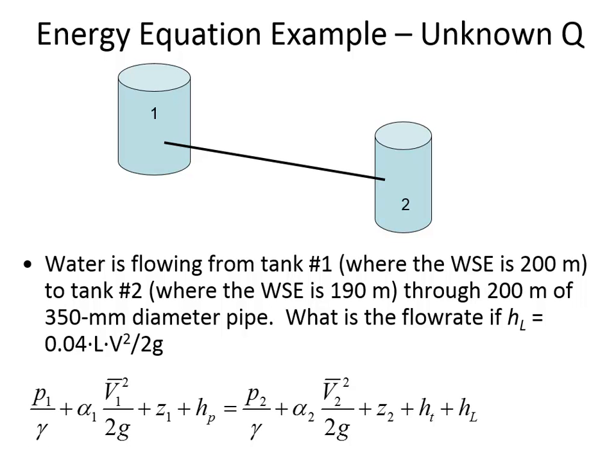If you connect a hose to a barrel, you can calculate the flow rate that should come out of the hose using this energy equation. You'd need to estimate what the friction losses are going to be in the hose, but it's a very useful idea that friction loss accounting allows us to estimate what the flow rate will be.